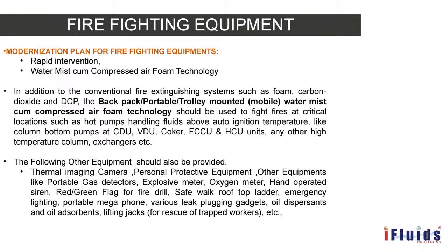In all these areas, there may be a probability of pumps handling fluid above the auto ignition temperature. So in all these areas we can provide this water mist cum compressed air foam technology along with the conventional extinguishers like foam, carbon dioxide, or DCP.